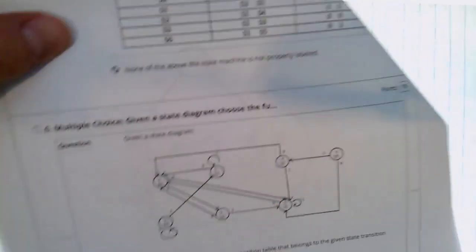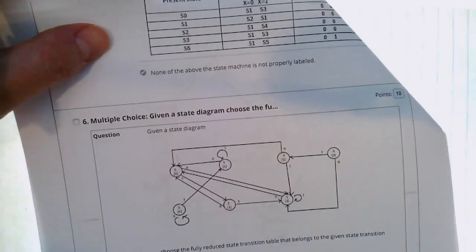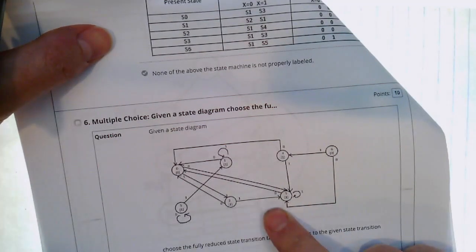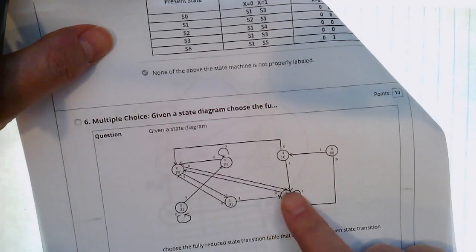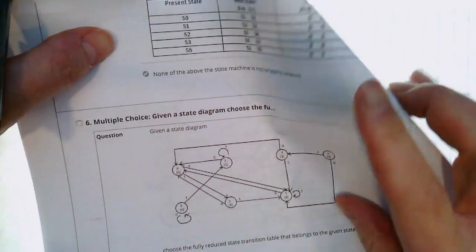First of all, is it a Moore machine or a Mealy machine? Moore or Mealy? That's a Mealy machine, true or false? You got a 50-50 shot. Somebody has to take it. What is it, Moore or Mealy? Moore, thank you. It's Moore because you've got outputs that are a function only of state, not of the input. So that makes it a synchronous Moore machine. And our states are numbered 0 through 6.